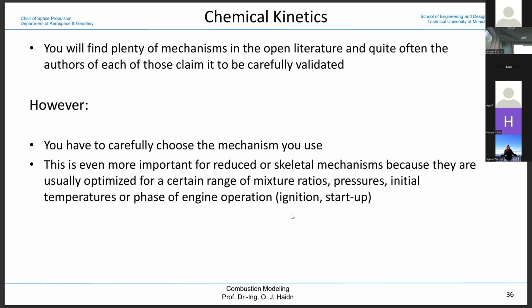So we would like to have not only the ignition, but also the steady state operation at high pressure, moderate pressure. That was the next step, keeping the ignition there, because in principle, since we inject our reactants with liquid oxygen, so it has to vaporize and it's cold, and also the methane is coming cold, so we have some low temperature. So the ignition process should still work even at higher pressure, because we go through the ignition first and then we go through the step of chemical reaction. So that's the reason why we kept the ignition mechanism for the small chemistry, and then step by step checked also into higher pressure. And now I think we are at 1.